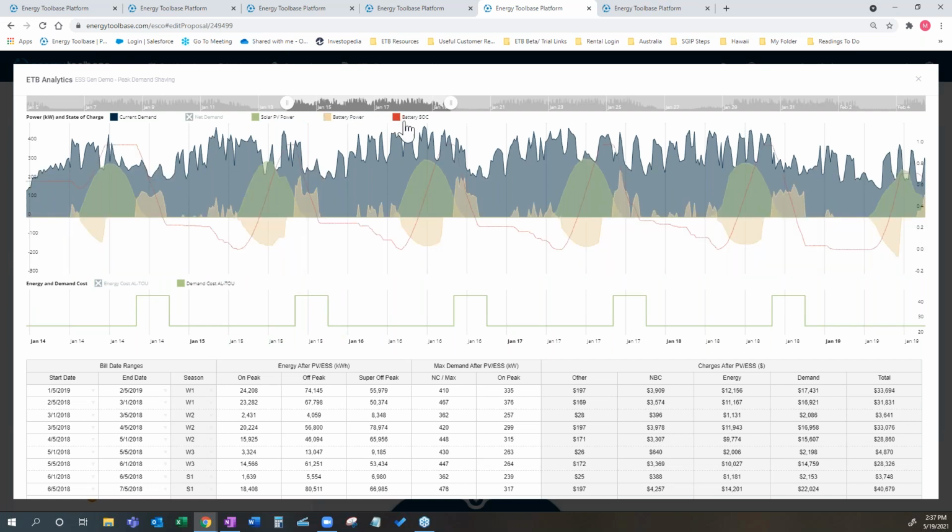Now let's go ahead and add our batteries. What we can see is that when our batteries are choosing to discharge, we can see all these spikes, especially during these shoulders. So we have solar PV making up a lot of this demand right here, but when PV winds down for the day, that's when our batteries are going to step in. So we can see that shaving very nicely, and looking at our net profile, we can actually see when the batteries are operating, we're shaving those peaks.